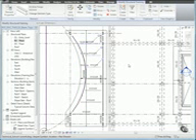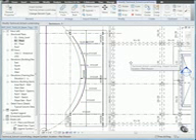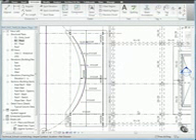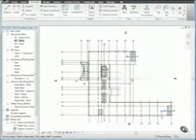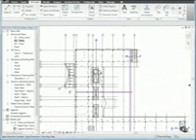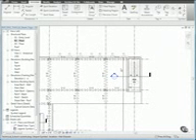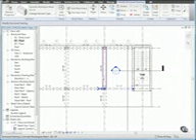Clear the selection, and let's create a custom type mark tag. Zoom to fit, and zoom in to the beams on the northeast corner of the structure. Then, click one of the 16 by 32 concrete beams, and from the Element Properties drop-down, select Type Properties, and in the Type Properties dialog, under Identity Data, for Type Mark, type C16, and click OK.